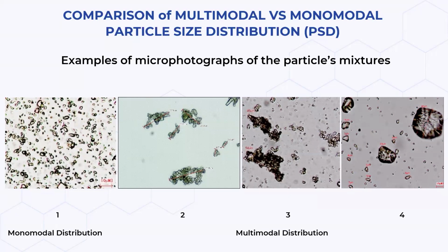For example, if the issue is with the formulation, you may need to adjust dispersants, wetting agents, or stabilizers. If the issue is with the milling process, adjusting bead size, milling time, or rotor speed can help. In some cases, switching to a more suitable grinding method may be necessary.